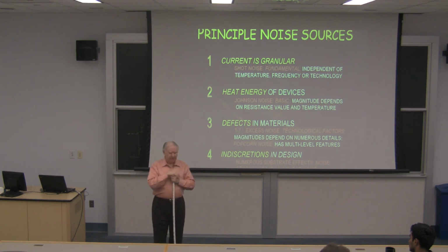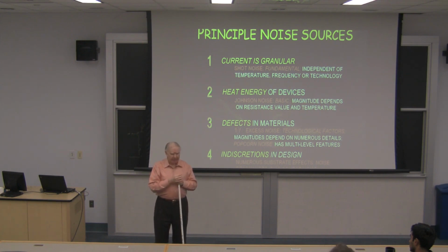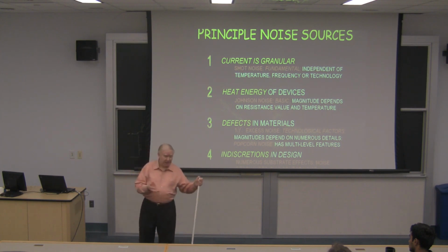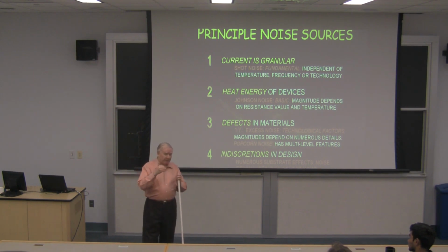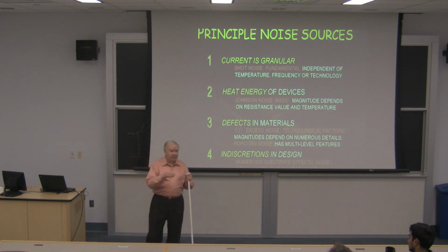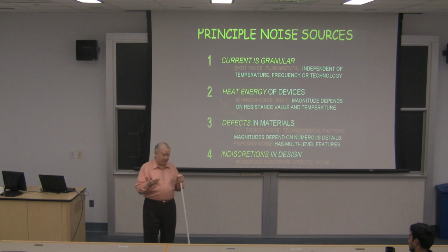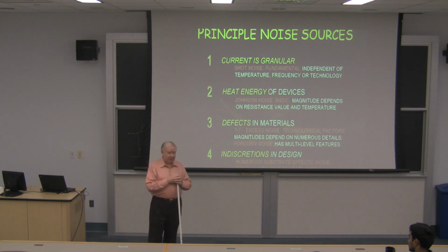I have this notion of a circuit having a certain personality, and that when you are performing experiments on your circuit to determine its robustness, which is a very important part of design. You know, we talk about PVT, process, voltage and temperature, voltage in this case meaning supply voltage, but every circuit exhibits a certain character, a certain personality of its own. And so in order to get it to tell the truth, you really should perform lots of sweeps of parameters. And of course the most obvious one is temperature. It's easy to do, but you can sweep many other things.